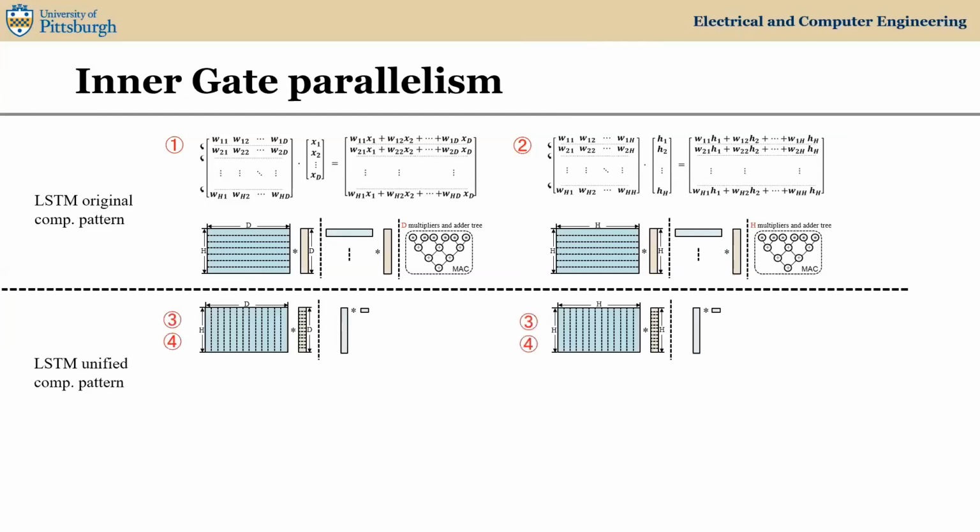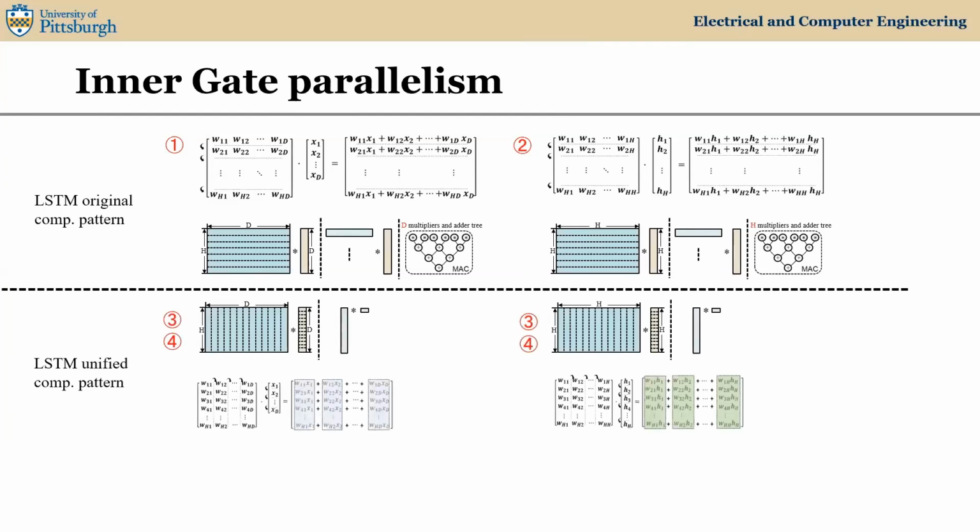First, each element of the vector multiplies its corresponding weight column. Second, we iterate over all the vector elements and their corresponding weight columns. Third, we accumulate the products of vector element and weight element in the same row. Therefore, the 2 MACs can be processed via pattern 3 and 4 as well. Pattern 1 and 2 have the same matrix rows, so the conversion for pattern 1 and 2 is in the same computing size, but in different iterations.